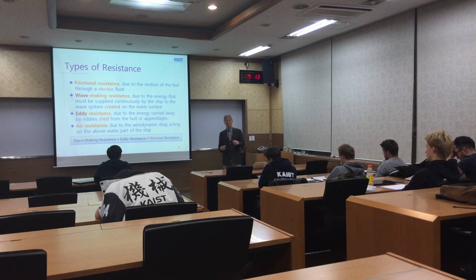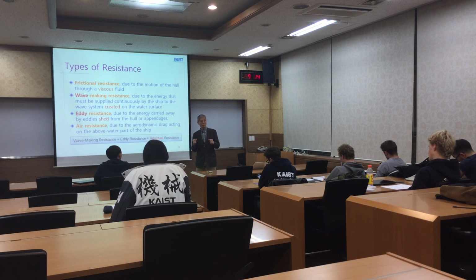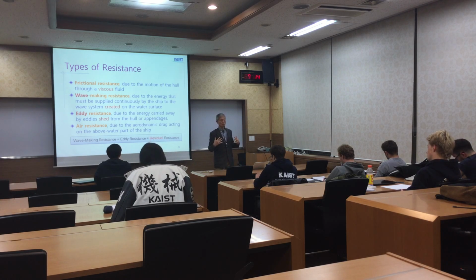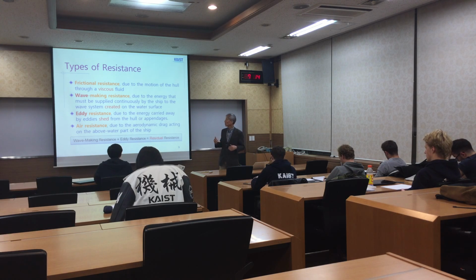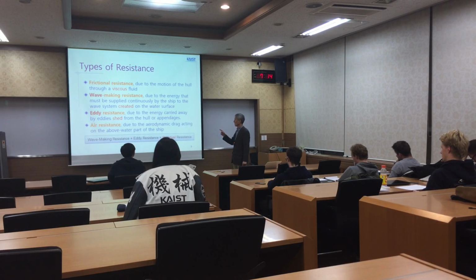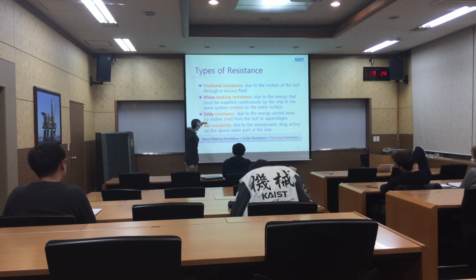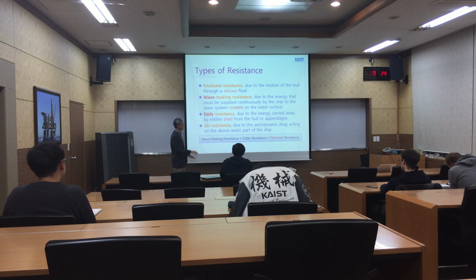Resistance is one force. When you're running inside the water, you feel the forces, right? Resistance. But for prediction, for the study, for the measurement, for the model test, we divide into components. So first one, frictional resistance, then wave resistance, and eddy resistance. And air resistance is above water. So this one is above water. The other three is for underbody, right, with the water.